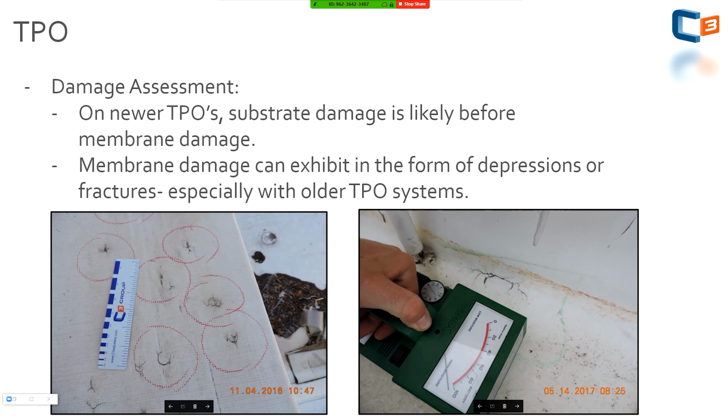And here's that Genflex TPO I was talking about on the left-hand side. So you look at that and you see the scrim. It's not a smooth texture like a lot of modern-day TPO membranes. And it actually fractured like PVC. So you look at that and you just have to realize that it might be either or. And the best place to do is go to a boot jack or a termination bar or somewhere where you can find a manufacturer's stamp.